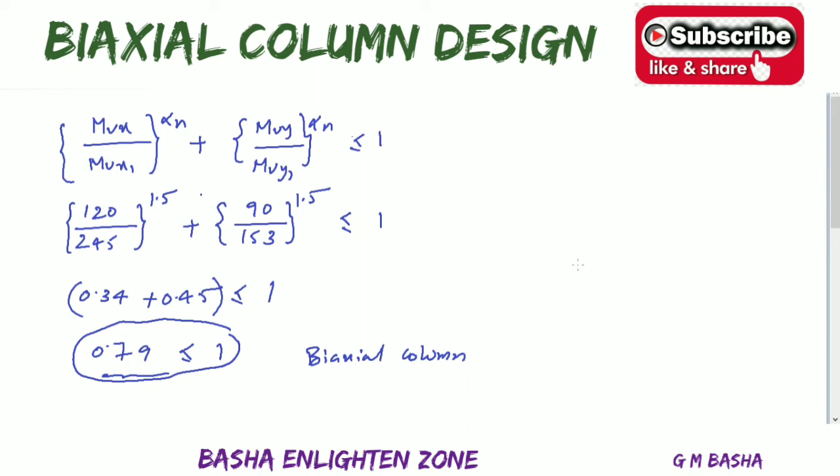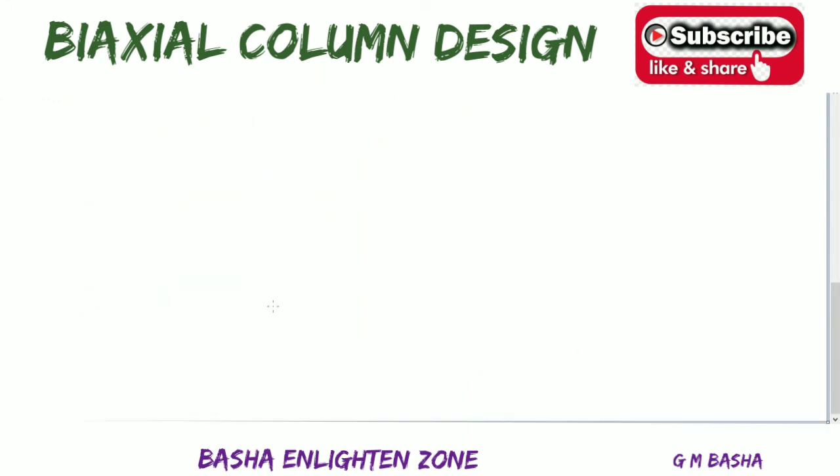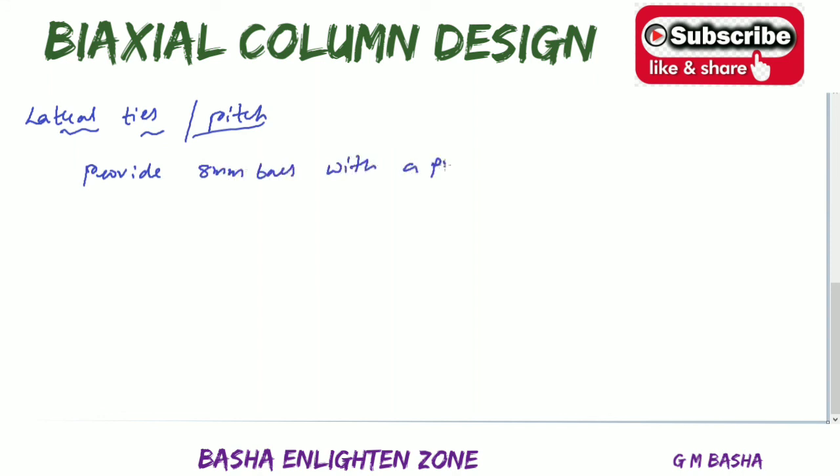Okay, then what is our next step? The next step is providing lateral ties and pitch. We solved so many problems based on lateral ties and pitch, like in the previous examples also. So roughly provide, according to the condition, 8 bars with a pitch of 300. Okay, if you want, you can see the conditions for pitch.